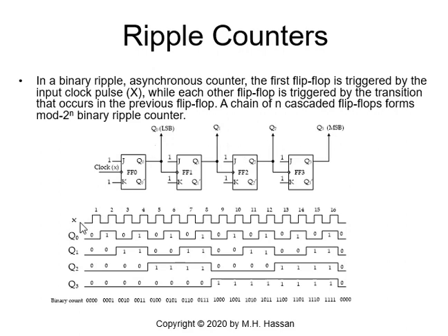Now, as you see, the clock is X. It changes from 0 to 1 at the negative edge, because all these flip-flops are negative edge triggered. Flip-flop 0 will be triggered at the negative edge, and you see Q0 will change from 0 to 1. This will go on: Q0 will change at every negative edge of each of the following pulses.